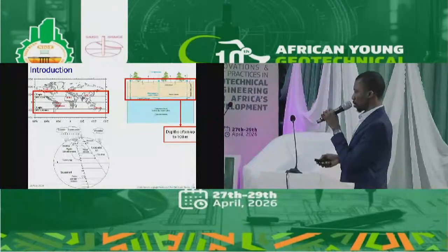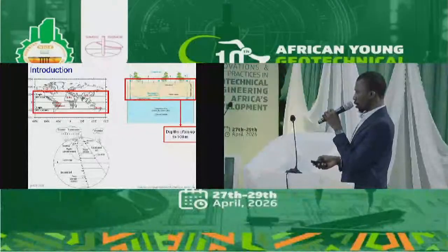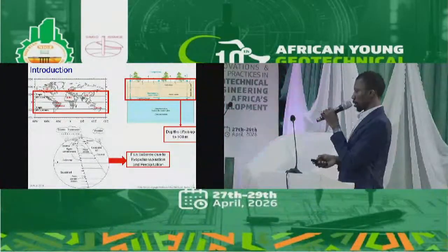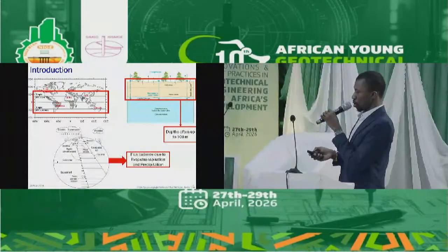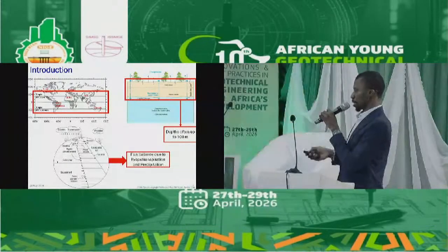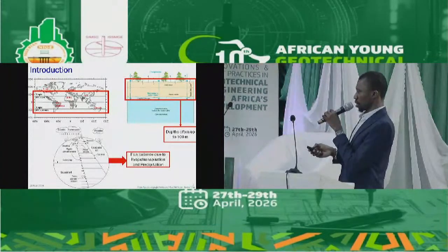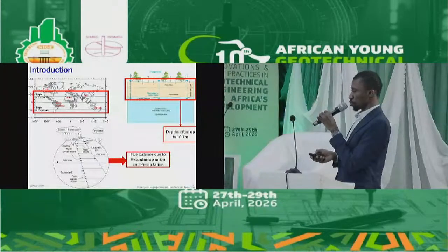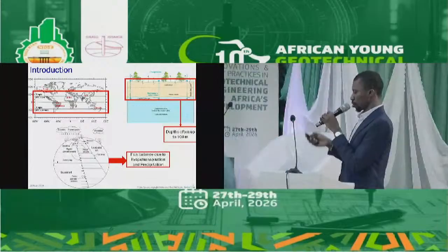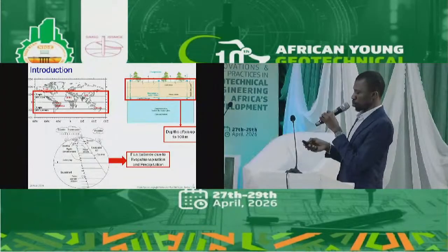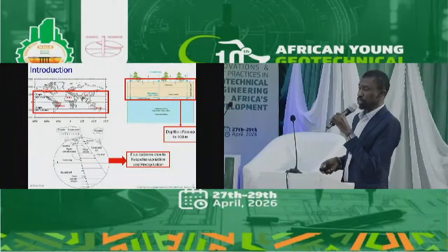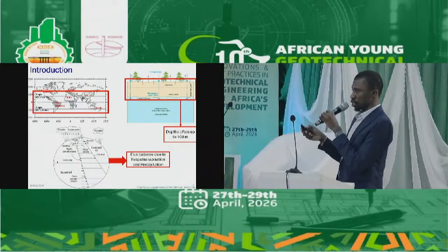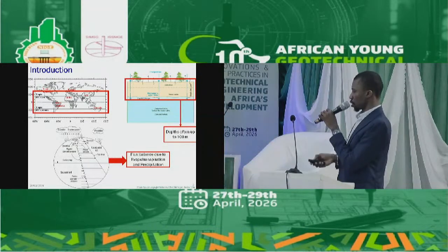for this behavior. And what actually causes this soil to be partially saturated? When rain falls, the soil becomes saturated during precipitation. But when the soil begins to dry, when sunshine comes, because of the amount of sunshine we have within the tropical regions, most of the water that has already gone into the soil gets evaporated. And because of that, we have a large change in suction, in flux balance within the soil.